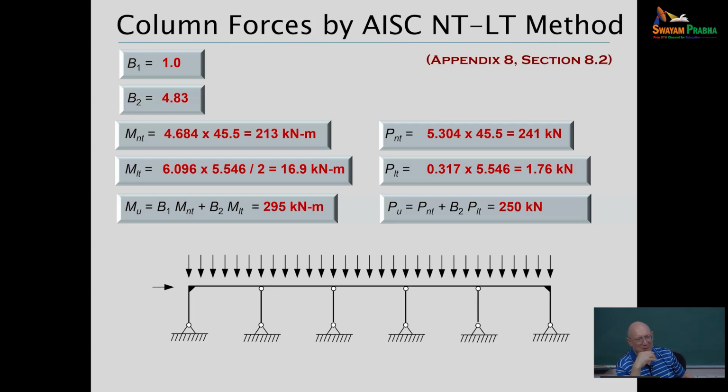So you could also look at this analysis. I analyzed this frame with a typical assumption that metal building designers would often use, and that's that I did not count on any rotational restraint at the base of the frame. Correct. And I was very interested to see that the Indian standard gave some very specific instructions on what you might use for a rotational stiffness to approximate some help you might be getting from incidental restraint from a foundation, right?